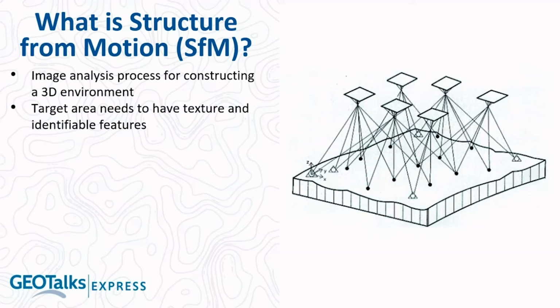Firstly, the target area that you're capturing images of needs to have texture and identifiable features. So this means that your images should be in focus. They shouldn't be too blurry. They need to have features that you can identify visually. So this doesn't work well with large areas of a single color, like areas of sky or snow cover. That can cause some issues with the reconstruction.